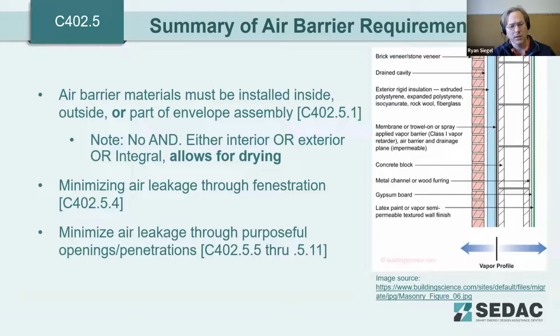Also part of this is trying to minimize air leakage around fenestration and purposeful penetrations and openings. Wherever you have penetrations for ductwork or line sets or plumbing piping, making sure that those get resealed and made totally continuous again.